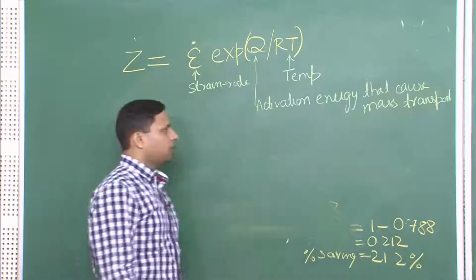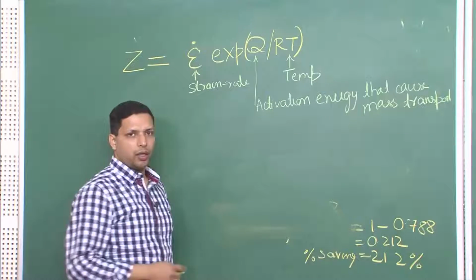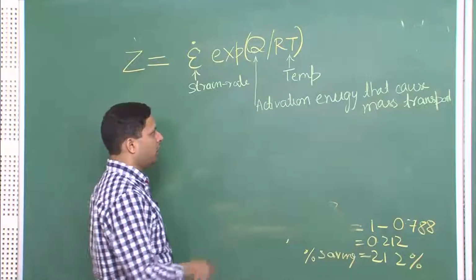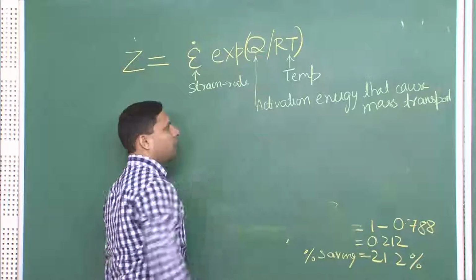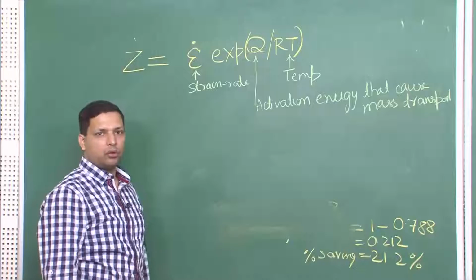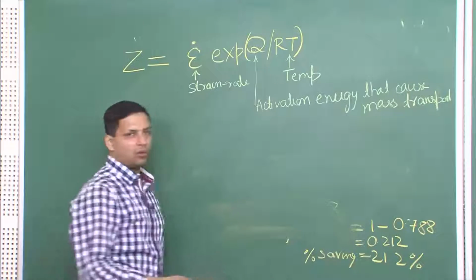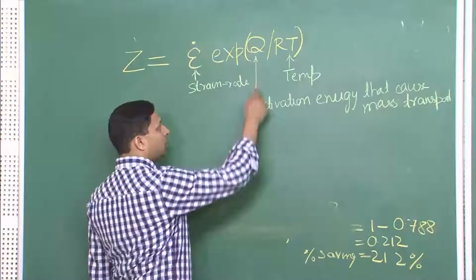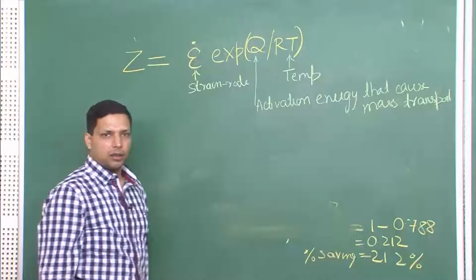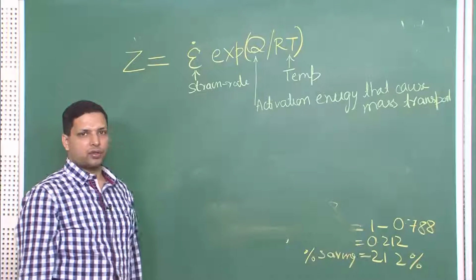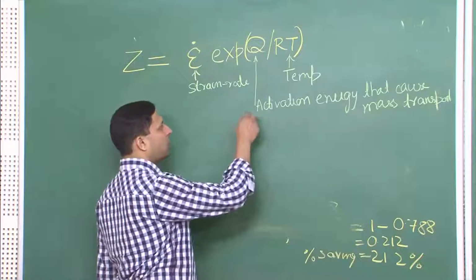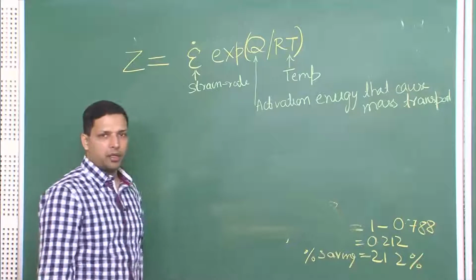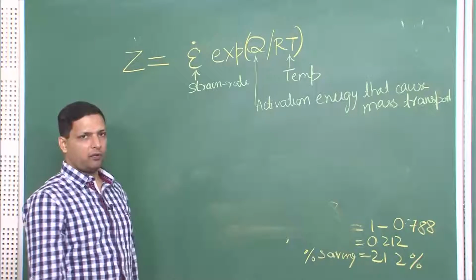So, for example, if we are doing a deformation where grain boundary is dominating, then this Q would be the activation energy for diffusion through grain boundaries. If you are talking about single crystal and doing the deformation, then Q would be the diffusion through the lattice. So, depending on the condition, configuration and the temperature range, the Q would be different. It will depend on you.